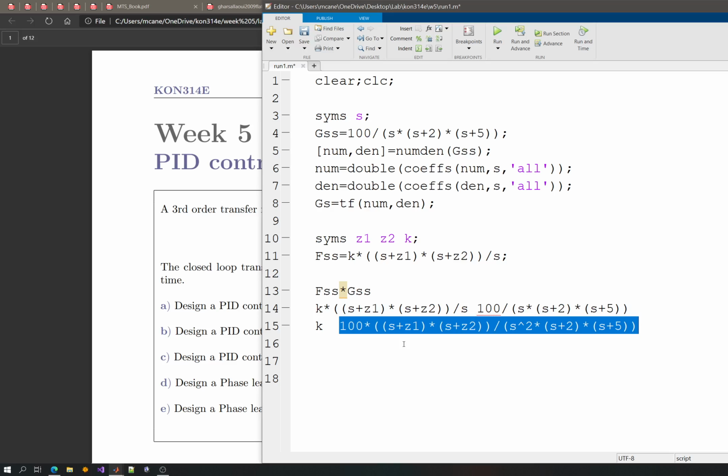Once you've done that, you use the new resulting root locus in order to design a P-type controller. Since you have decided on the zeros of the controller and you know where the pole is, you add these zeros and poles to the system, and the resulting new system is used just for the calculation of the gain. So when you have chosen your gain, you're done with your controller design.